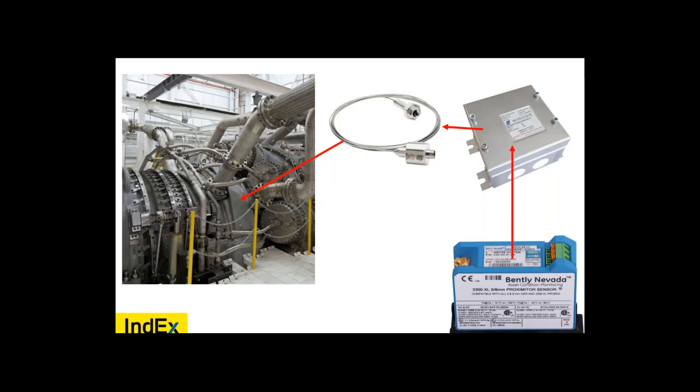EX ec, all of your internal components would have to be EX ec. So all your terminals could no longer be EX nA. So that transition period from one edition to another causes many problems for manufacturers. Okay? Is it mandatory that all internal components need to be EX certified? For EX e and nA, yes.